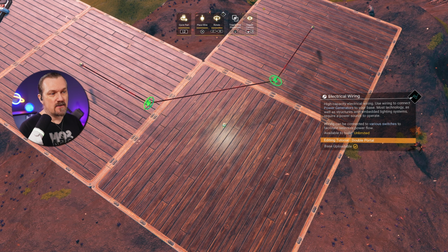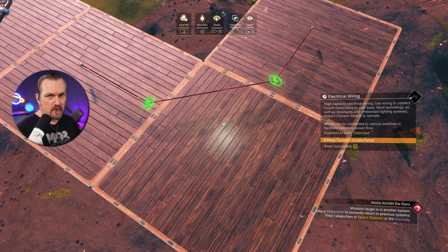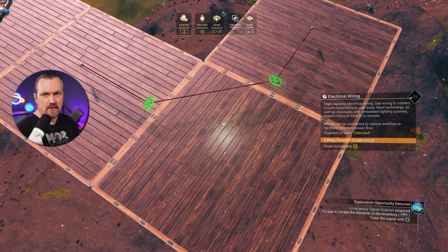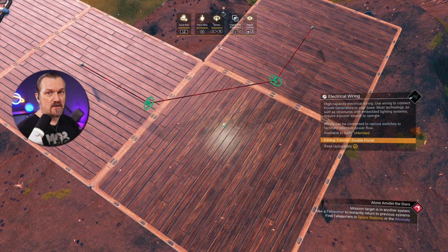Now, it is possible to snap 10 wires to the same center point, and then the wire connection disappears. But it is very, very difficult and confusing to glitch all of these on the same center point if you have 9 wires connected to that center point, because the rotation doesn't work properly and it will sometimes glitch on the same point, and you don't want to do that. So the best thing to do is always just prepare your snapping and connection points outside and then pull each wire separately to that center point, glitch on it, and then replace it with the new direction. That's going to be much easier to manage.